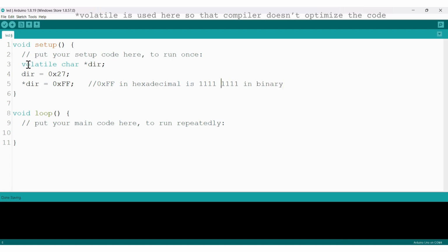So what we're doing is initializing the 8 registers we have as output, because we're going to glow an LED on that. As the port C address is 0x27 and we want all the pins on that port to act as outputs, that's why we're going to put 0xff.